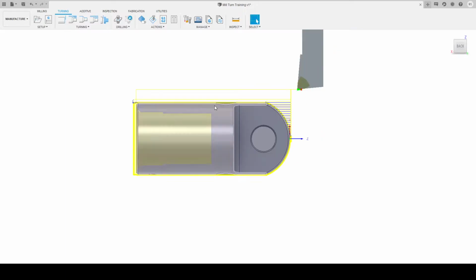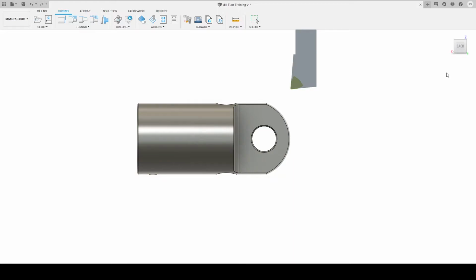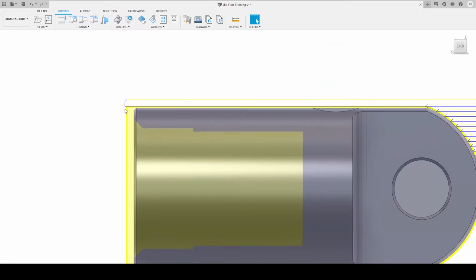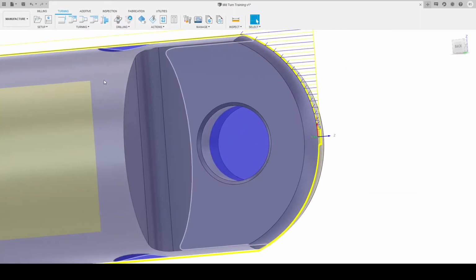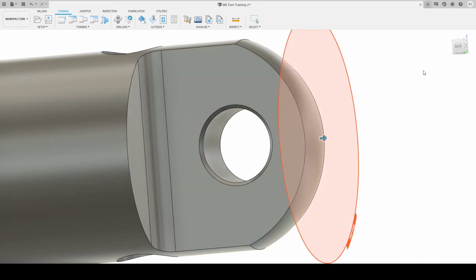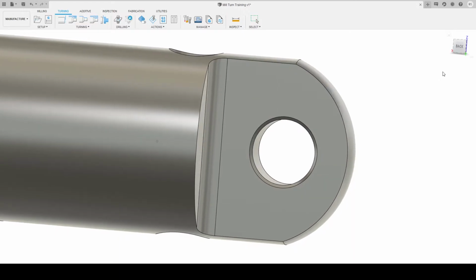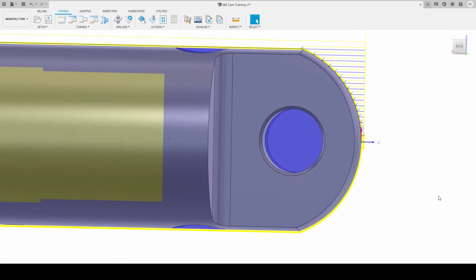So we'll click close. We'll edit our toolpath. And then in the second to last tab, the passes tab, you have this grooving option here. So if we click don't allow grooving and then OK, you'll see that we actually get a straight toolpath off the back. Looks good.